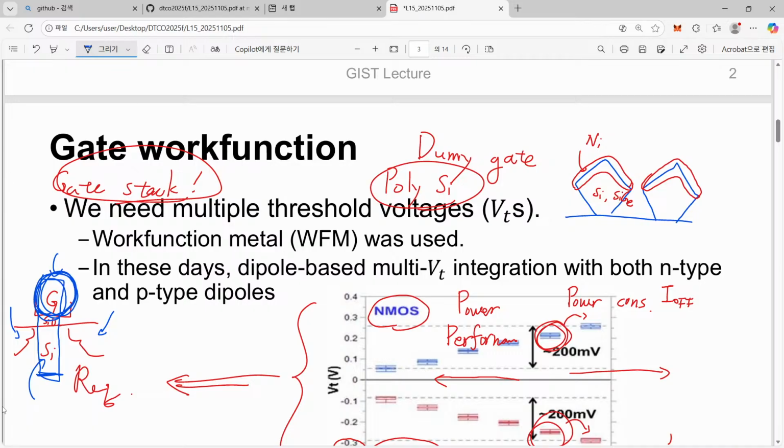That was changing the doping density, acceptor density or donor density, for N MOSFET and P MOSFET. That was the way to control threshold voltage. Simply speaking, if you provide more and more impurities into your silicon substrate, then you can increase threshold voltage. And if you don't have enough doping density, then your threshold voltage in terms of its absolute value is reduced and goes close to zero.